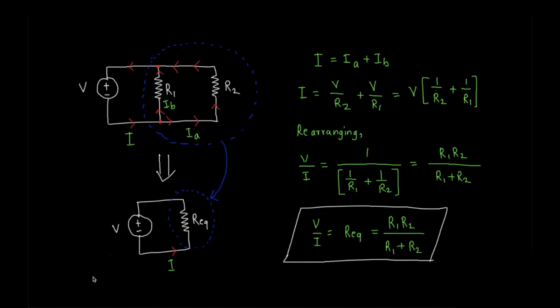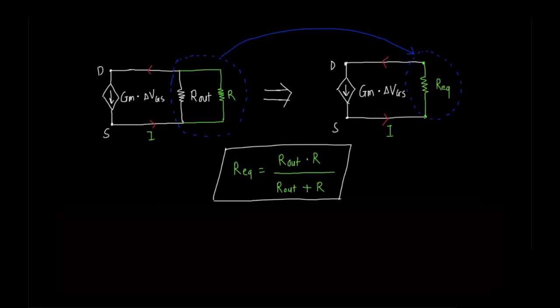Let's take simple circuit with two parallel resistors. By doing fairly simple calculation, we can get to expression of current split. We can also imagine combination of two resistors as a single resistor of value which you can calculate by formula you are seeing right now. Pause here if you want to stare on this some more. Now let's get back to our circuit. Replacing two resistors with their equivalent one resistor, we will get the gain of Gm times R total, where R total can be found using the equation we just saw.